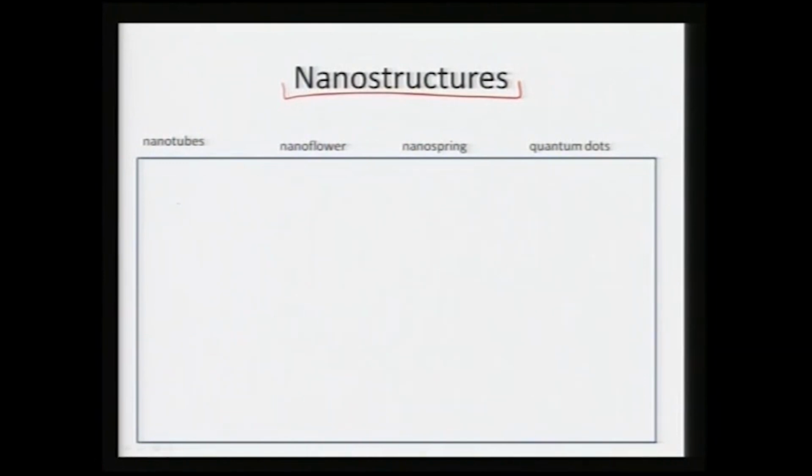It can be nanotubes, in which case we can have boron nitride nanotubes or carbon nanotubes. In this case, a kind of sheet is rolled to form an entity of a hollow tubular nature. So, we can see it has a certain thickness, and that now has been rolled to form a certain tubular shape. It is no more a rod, it has some hollow structure, and the diameter of this particular tube is on the order of a couple of nanometers, whereas the length can vary from a couple of nanometers to a couple of micrometers.